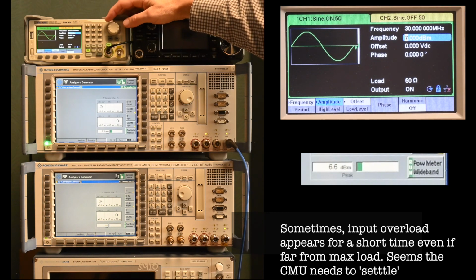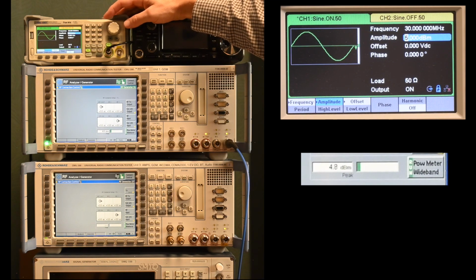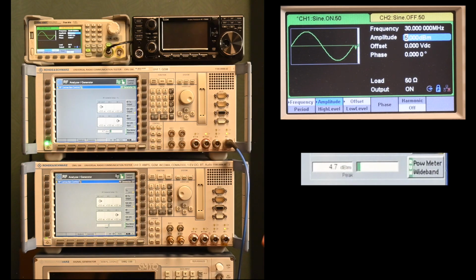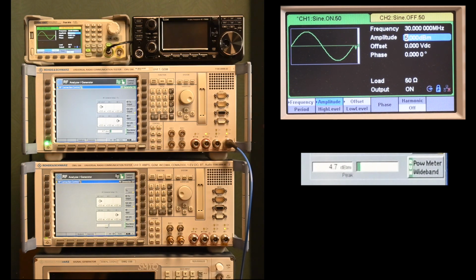The device should be able to handle 50 watts or so, but sometimes we get this power overload. Okay, we got rid of it. I think it needs to reset itself. Now I'm going to send in a signal of 5 dBm, and in the wideband meter this is recognized at 4.8 or so. Now that's perfectly possible. I might have some cable losses. Maybe this unit is not perfectly calibrated, or the CMU, but I would say close enough.